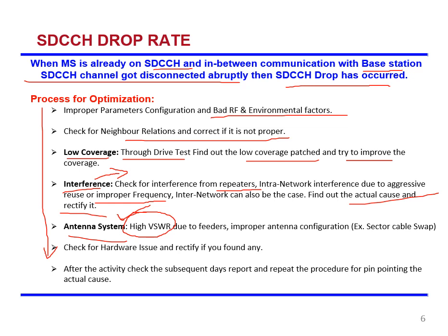Ideally 100% of the energy you are radiating should be transmitted. The 100% of the energy you are radiating at the base station is not being transmitted from the antenna. It means there is an impedance mismatch and the incident power is being reflected. And how to avoid it? A simple way to check it is to change the cable, swap between the sectors and check it.